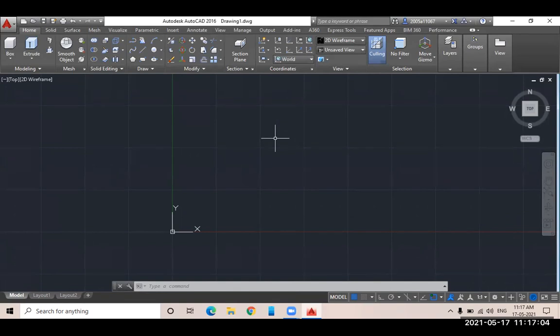You just need to click on this gear option, and thereafter you can change your workspace settings. Okay, so if it is not visible in 3D basics, you can switch to 3D modeling. If some icons are not coming in 3D modeling, you can change to drafting and then come back again to 3D modeling. Then by default all your commands will be restored. Okay, so this is what I want to show you on the Windows system, if it works like this.